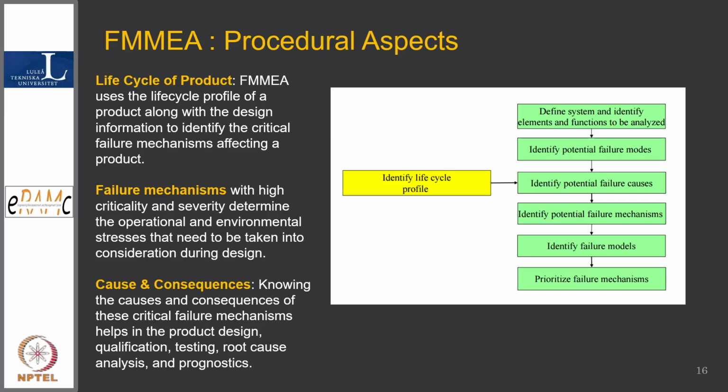If there are certain locations that see magnetic field effects, my electronics should be developed and validated for those kinds of effects. Then there is the seashore. If I am putting some electronic component there, the humidity is very high. Humidity and temperature are the two enemies of electronics. Dust, of course, is also. So we have to take into account the life cycle of the product.